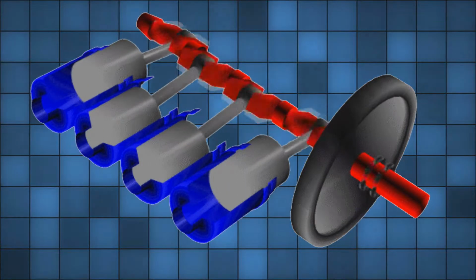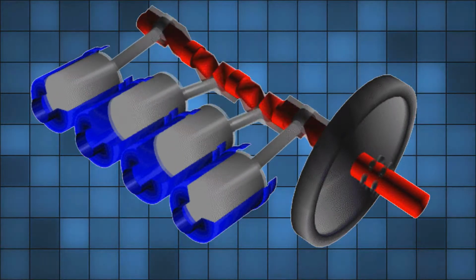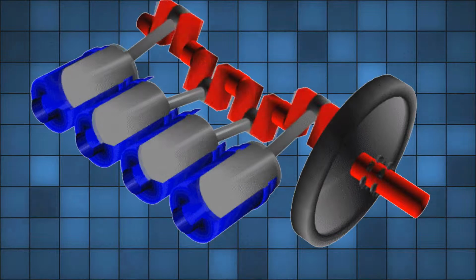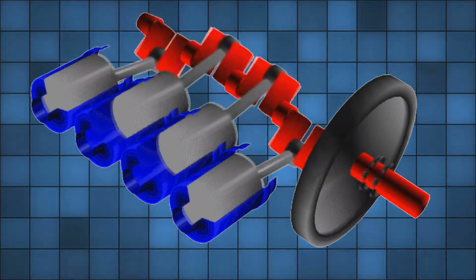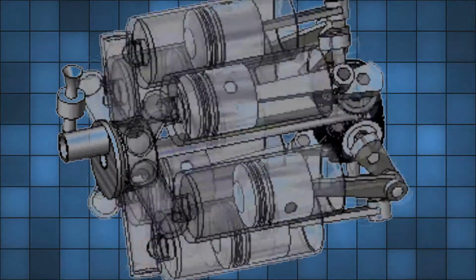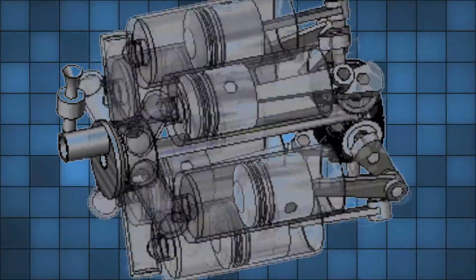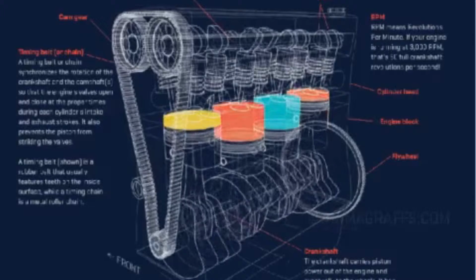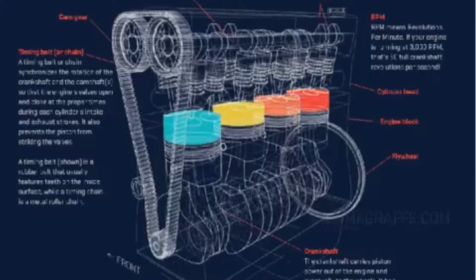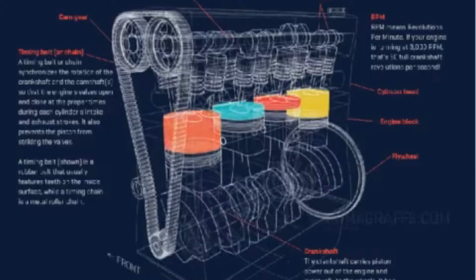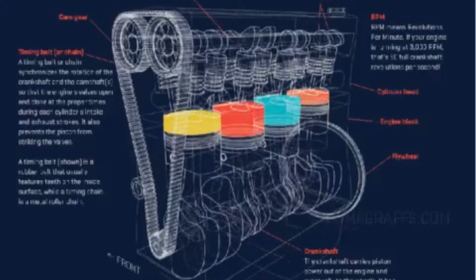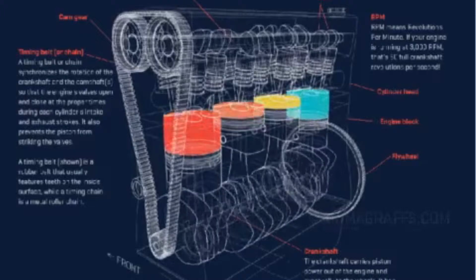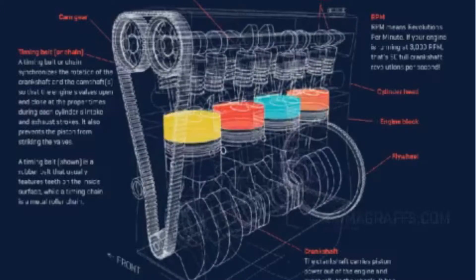Built-in limitations of reciprocating engines. First, the reciprocating action of the piston sliding back and forth in the cylinders causes vibrations and significant internal stresses for which the engine must be designed. As a result, they are heavy for the power they produce. Second, they have a large number of moving parts that require the engine to be overhauled when relatively few hours of operation have been accumulated. And lastly, the only way to produce thrust is by driving a propeller.